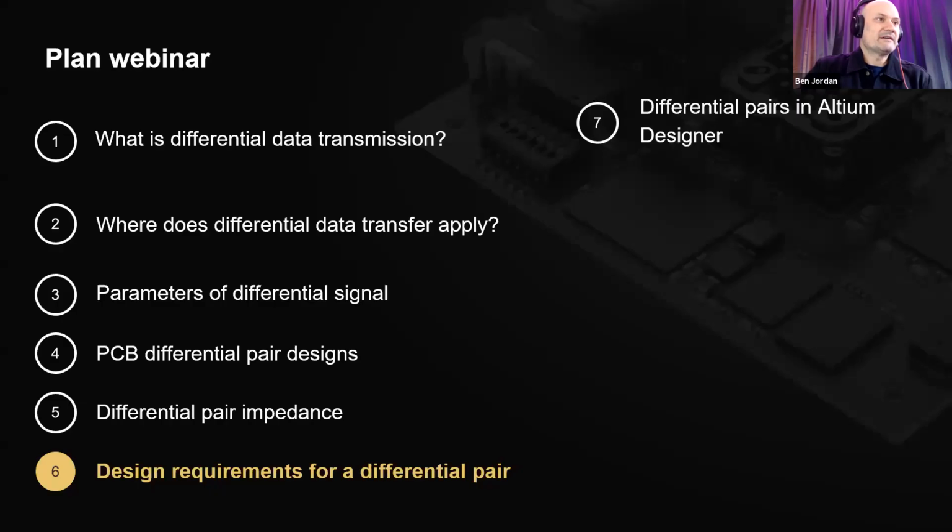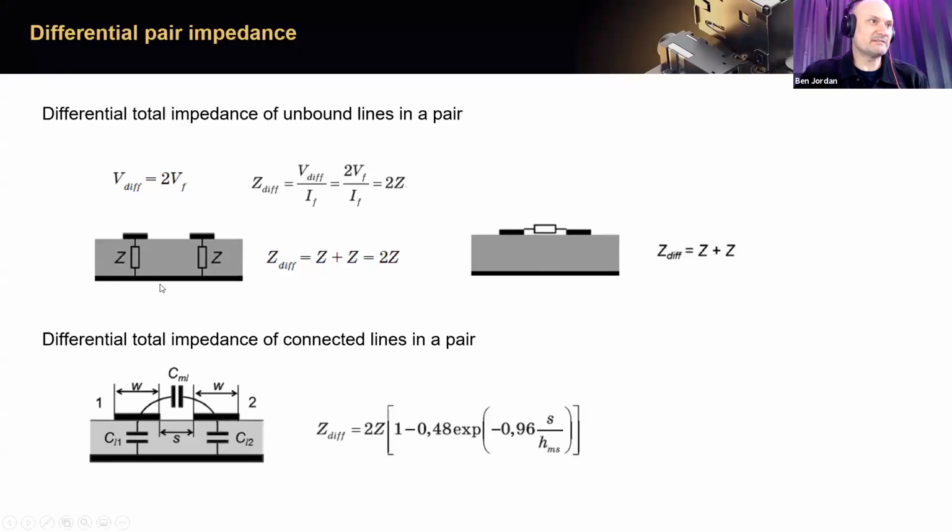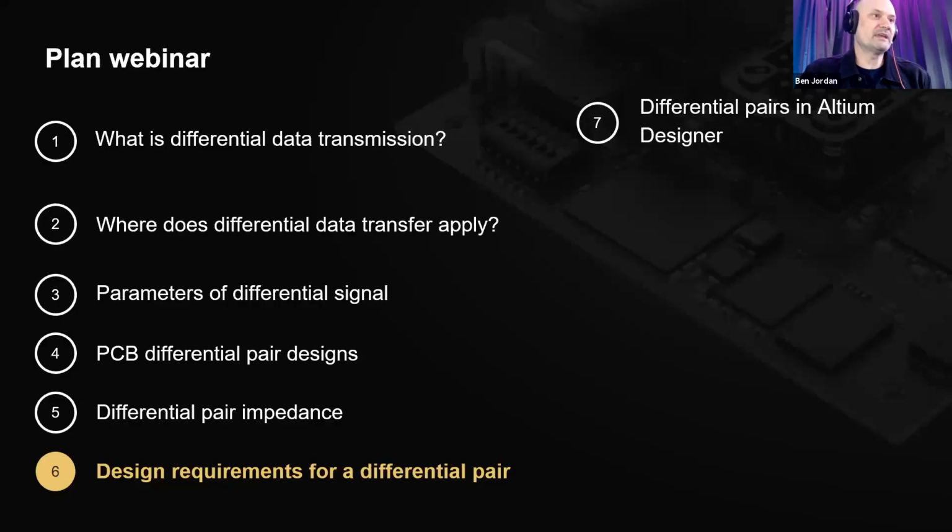Okay, and so we can get more accurate than that using a static field solver, which we'll talk about in a little bit. The static field solver uses techniques like breaking up and measuring capacitance, like ATLC that generated those images before does it the same way. And there are other algorithms used as well, of course, like FDTD and so on.